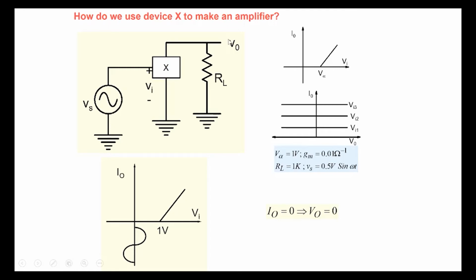So the issue before us is that we don't have an ideal transistor. We said an ideal transistor is not available. What you will have are elements with all kinds of non-idealities. So suppose we have a non-ideality like this here. Then if we simply connect an input to this kind of non-ideal transistor, it's not going to amplify. Note that in this case it is 0.5 volt, and we may be talking about signals which are even weaker, maybe 1 millivolt here. So it would be very close to the origin here, and therefore the current is 0 and the amplifier will not work.